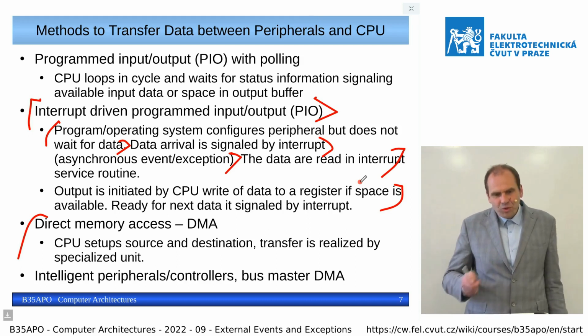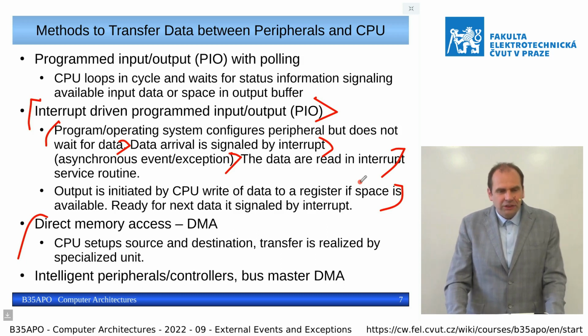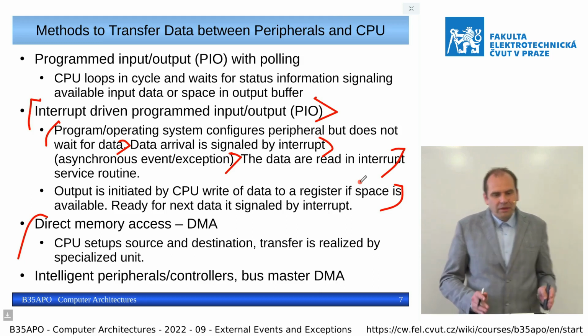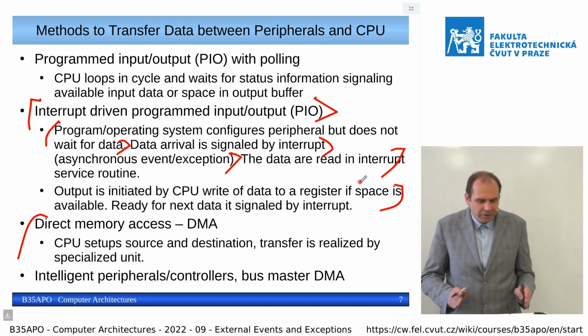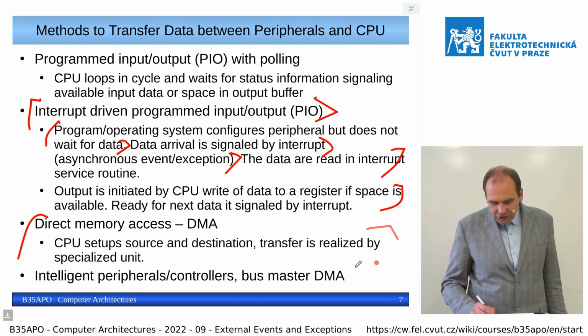So basically, you have there some FIFO-like mechanism which ensures that even if there is some small lag in the CPU, you do not make a gap in the output sound, but you basically keep the FIFO somewhere between half and full. So this is the mechanism which uses a DMA.